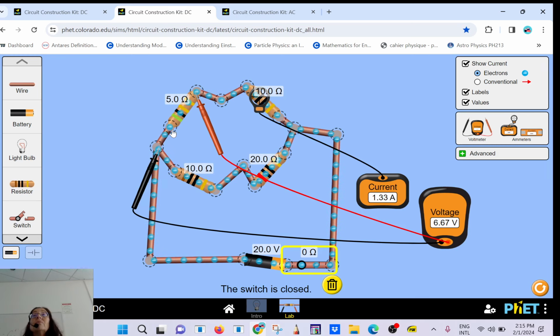So if I ask you which one will be the brightest, it's going to be the 60. Which one has the largest resistance? It's going to be the 40. Now, if I do something that we never do: I have the 40 watt, a big resistance, and I put that in series with the 60 watt.